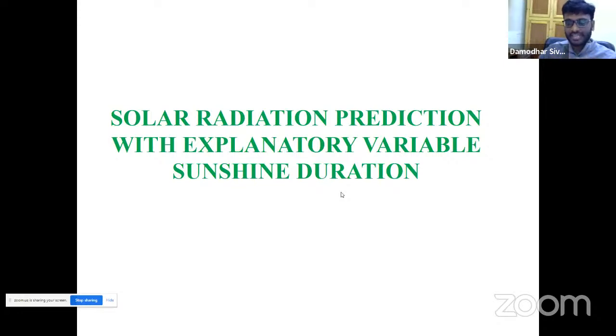We have a sunrise time and a sunset time. From the sunrise time to the sunset time, on average, I can tell you that it can be 8 hours to 13 hours depending upon the latitude of the location. So we have a total sunrise to sunset time, say 8 to 9 hours. This is the time where we can generate solar power output from the system, which you can then integrate to the grid.